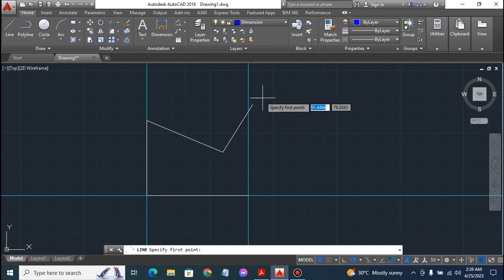We also have what we call the extension line. Even without clicking on the end of the line, when you just place your cursor at the end of the line and then take it away, you see a line that is extended, that aligns with the line we have already drawn. That is the extension line. So we want to produce a line at 90 degrees with a distance of 30. So click on the end of this line.